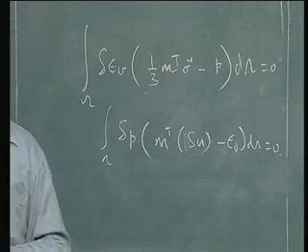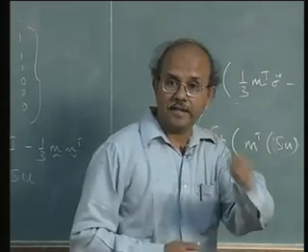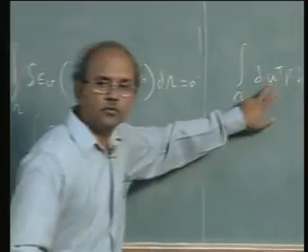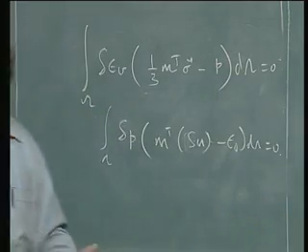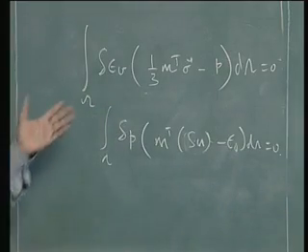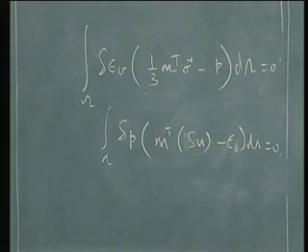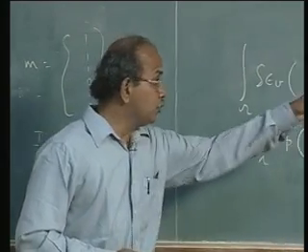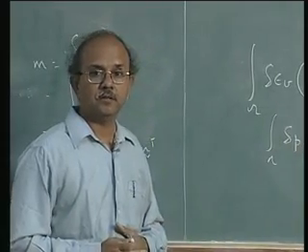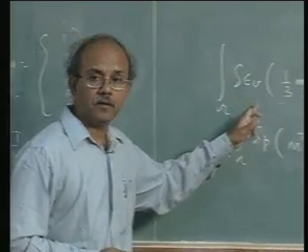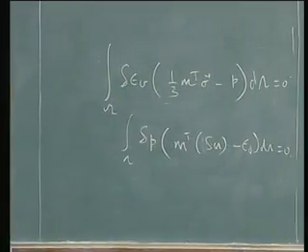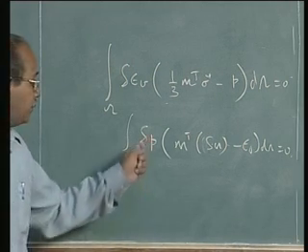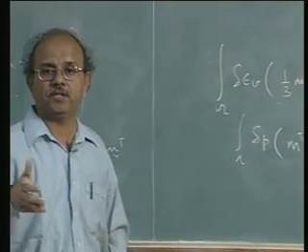We said that we are going to have three things. Like we had delta u in the first case, we should also have variation in p as well as in epsilon v. So those two also enter into the picture. Delta u is a virtual displacement. Delta epsilon v is the variation in the volumetric strain. Delta p is the variation in the pressure, right?